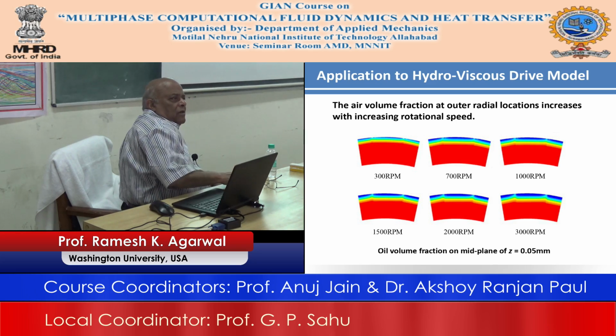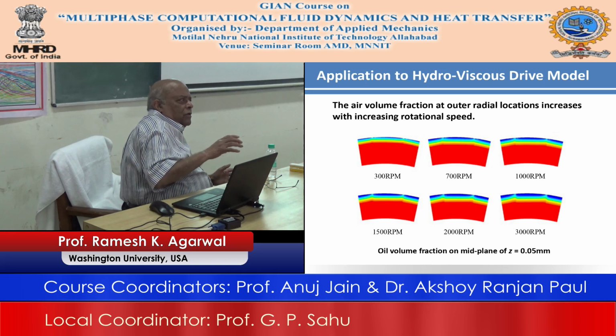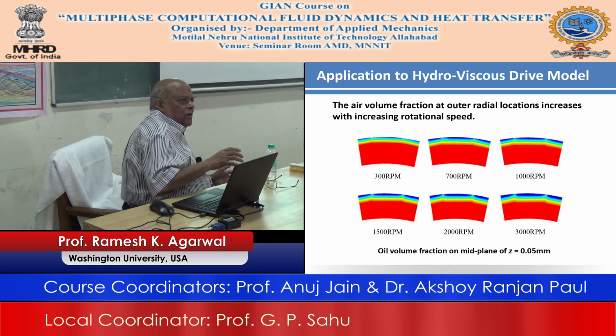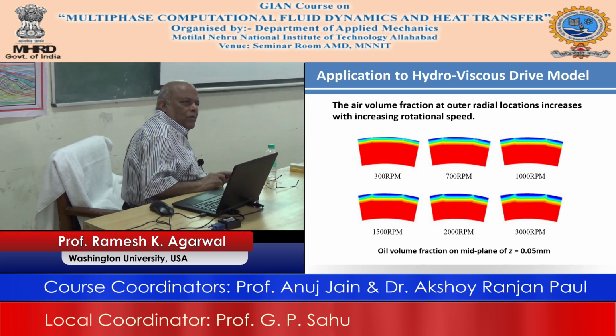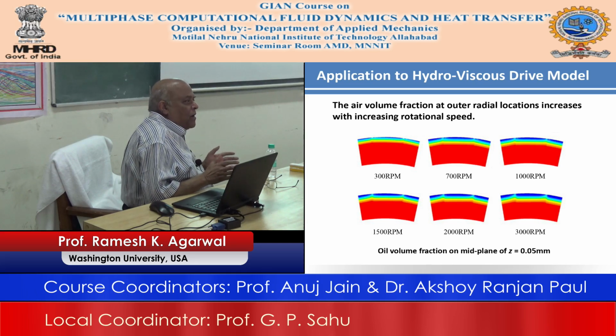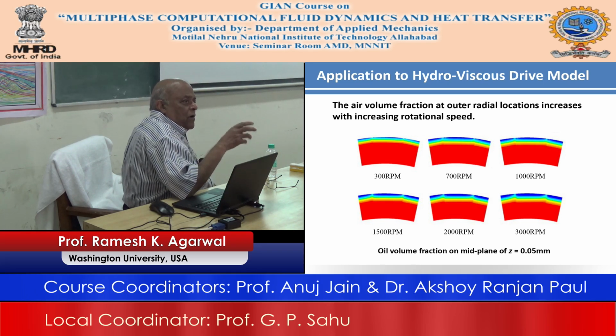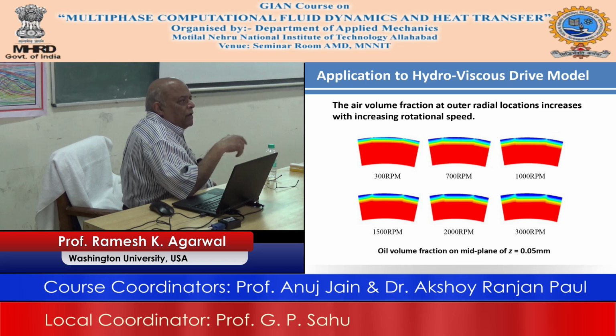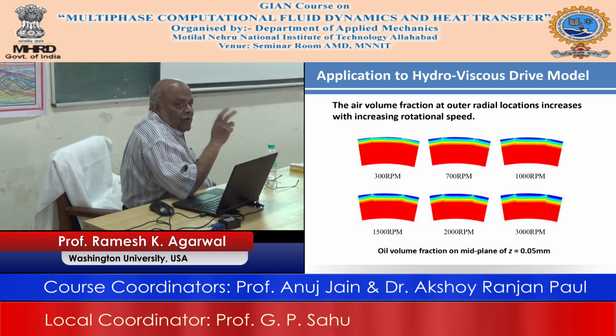So, what is happening is that for the flow conditions and operating conditions that you are interested in, you have developed cavitation for this simple model or simple case, and it is a very good problem. You may think that it looks too simple a problem, but it is a very good problem in terms of the application, because it is part of clutches and many other machinery. So, what it goes on to show is that the performance of the drive will deteriorate at higher speeds. So, how do you change that? That is the second question.